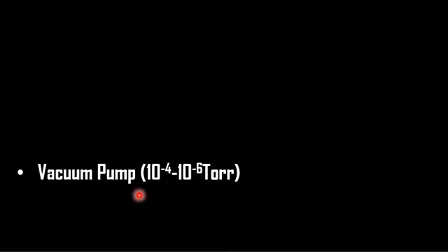Please note that the closed space sublimation apparatus is connected with a vacuum pump. You can deposit thin film at atmospheric pressure. However, low vacuum pressure is preferred for any vacuum deposition process because low vacuum pressure gives you an opportunity to deposit a uniform film on the surface of the substrate. The pressure usually used in the reaction chamber of the closed space sublimation apparatus is in the range of 10 raised to power minus 4 to 10 raised to power minus 6 torr.